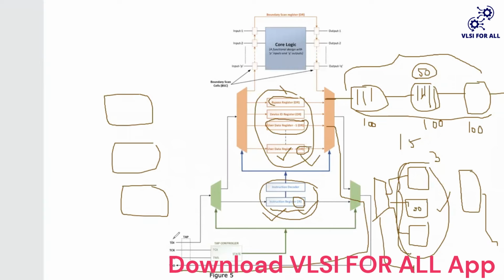So first, we will push the data from this TDI and select this register through the selection mux, and this will be getting selected. Then we will push in the data, whatever we need to program. And similarly, we will observe the data from this one to here. Is it clear now? Yes, sir. Okay, good.